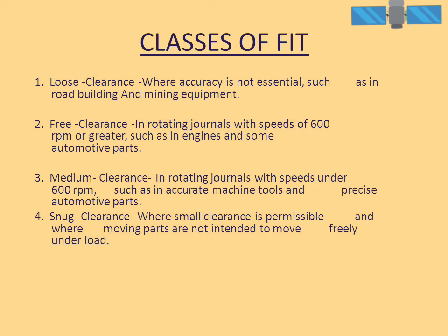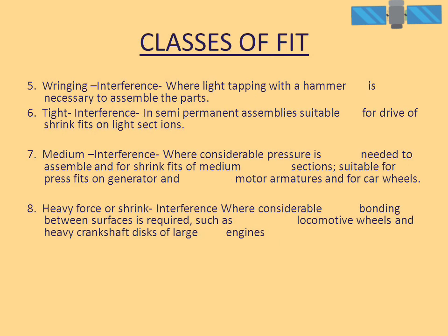4. Snug clearance where small clearance is permissible and where moving parts are not intended to move freely under load. Classes of fit. 5. Ringing interference where light tapping with a hammer is necessary to assemble the parts. 6. Tight interference in semi-permanent assemblies suitable for drive or shrink fits on light sections.